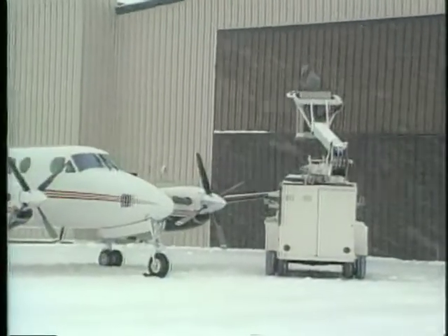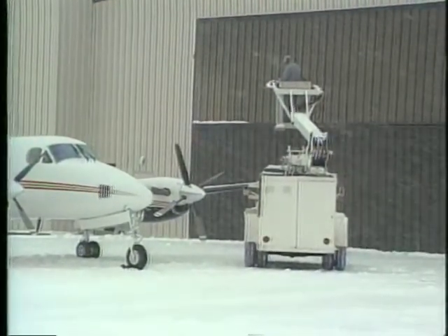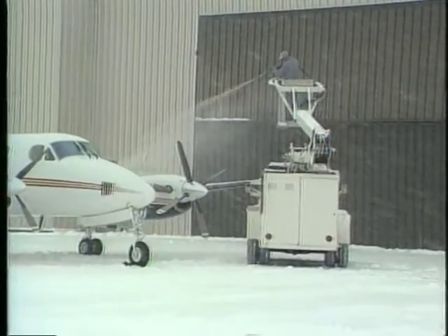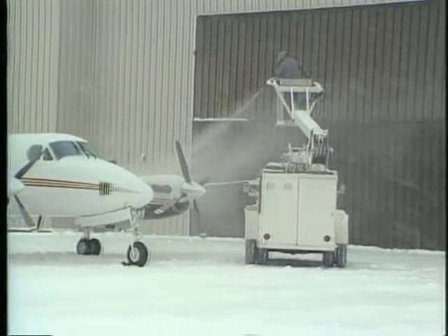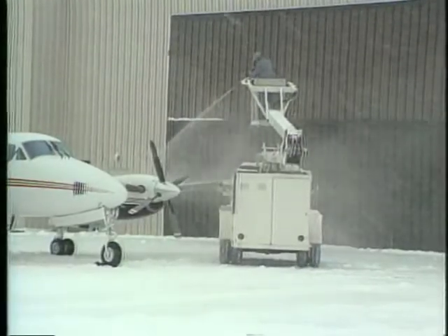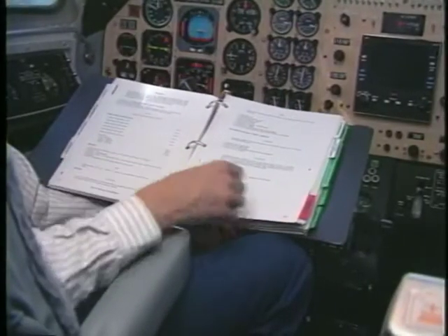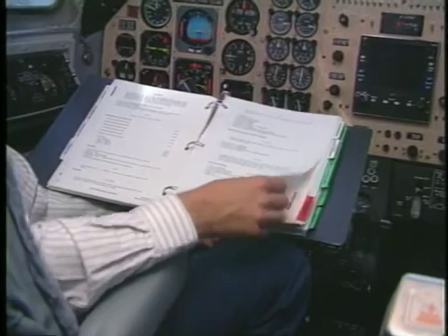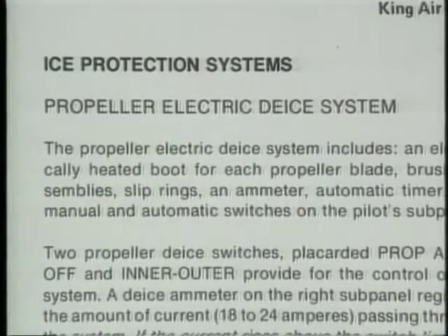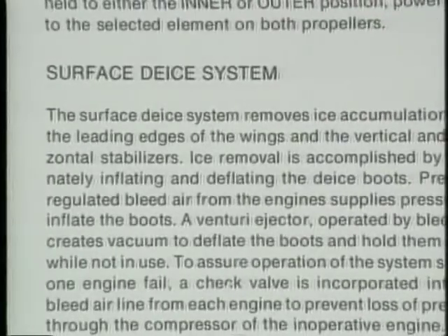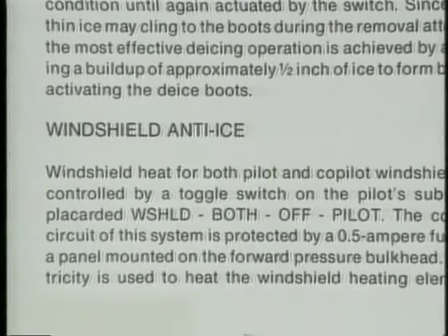Before flight, anti-icing chemicals may be applied to the airframe, propellers, and windshield to lessen the chance of ice adhering to these parts. Used together with anti-icing and de-icing systems, these chemicals can be very effective. Of course, flight in icing conditions may be hazardous regardless of how your aircraft is equipped. Before you enter areas of known icing, you should be sure that all of your systems are operating correctly and that you're familiar with the specific equipment installed on your aircraft. It's also a good idea to limit your exposure to icing conditions. Some of the systems described may handle ice better than others.